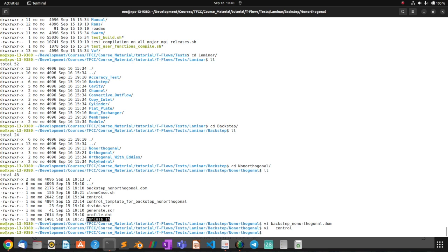But what I want to do now with you is to decouple, or dissect, what these automation scripts have. So that said, we can start already by generating the mesh. For generating the mesh, we need the program generate, and that is just a script here that submits the main keywords to generate the mesh.